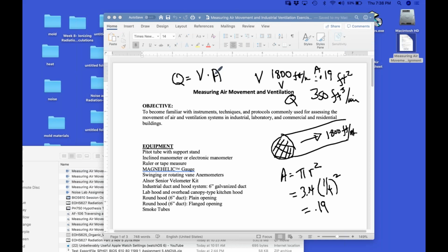Okay, so now try to get 6 inches away from the base of the hood. Look over against the hood. Yeah, there you go. It's 6 inches. Okay, good. And then the other hand away in the center. Whatever it is now, 116 feet per minute. Oh, that's decreasing. So it decreases as you get further and further away.